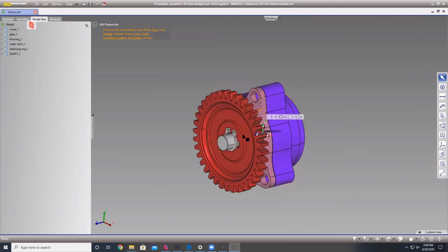Since I'm building this assembly with parts that have been provided independently, in order for this to end up in the correct location, I had to convert these parts to absolute positioning. That's something that you do with the tool called assembly conversion in 3D Evolution, and I touched a bit on this in one of the first presentations. This allows you to take the parts out of their context in their assembly and then put them back and rebuild with anything else that you want. So that's part of what I did.